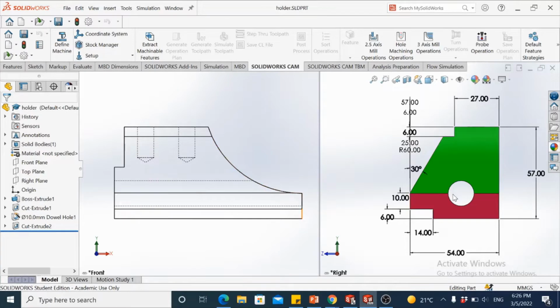The third one that we have is the circular sketch entity here. As we project lines, we find that it runs through from the curved surface over here. So a portion of it lies on the curved surface, the rest is on the planar surface that we have here. As it runs through the surface, it goes all the way till the end, drilling a hole as indicated by these 2 hidden lines. So it's basically a hole, and we see the true shape of the circle in the right side view. So this is all about what we have from the right side.